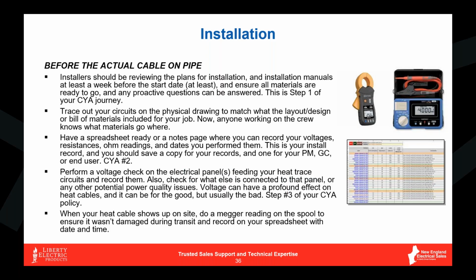Generally, nobody has a problem with it when it's on the hot side. It's the low side we're trying to worry about. So again, record that voltage to start off with. You also want to measure these cables like crazy. So when materials show up, you want to measure these cables, make sure nothing was damaged during the freight, and note it. So again, everybody's aware that everything was good with this on such and such a day, at such and such a time.